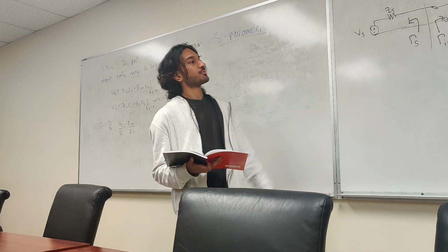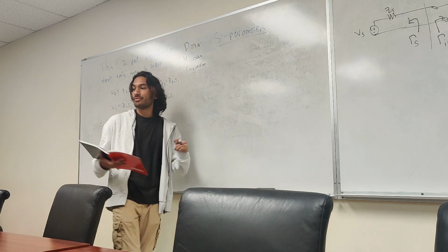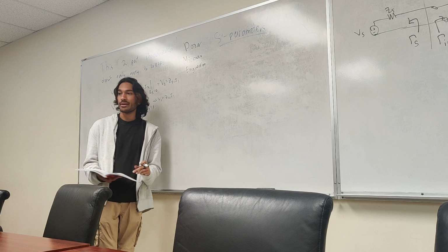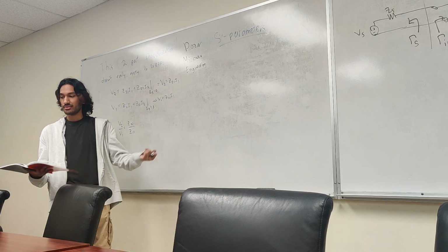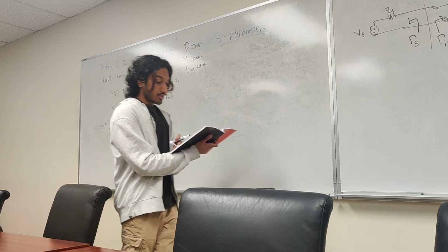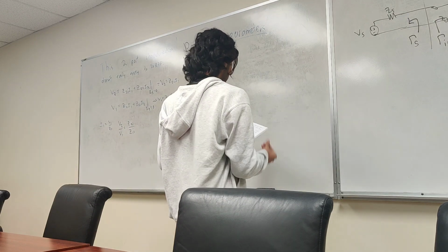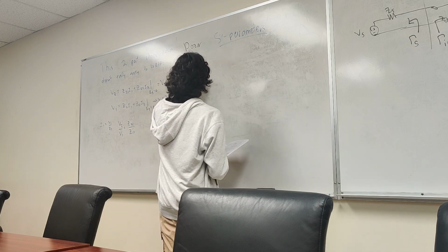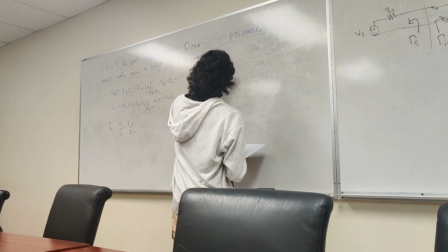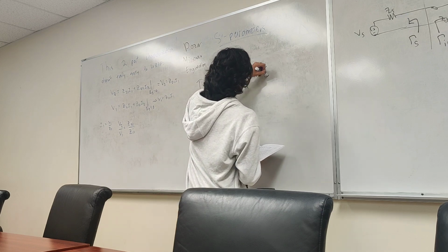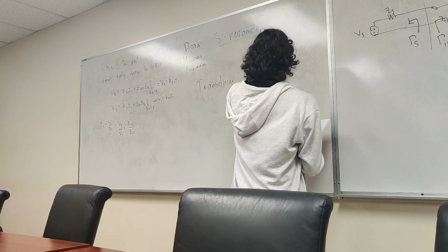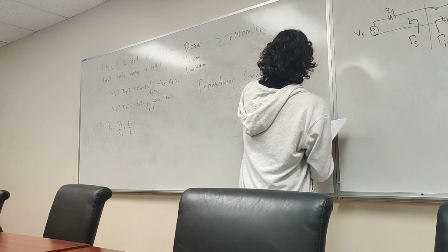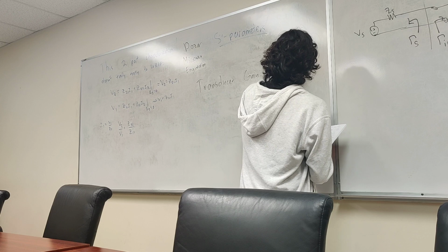So, we want to squeeze out as much gain as we can out of this transistor, so we want to define gain somehow. If we know what parameters gain consists of, then we can try to maximize it. If we have no idea what gain is related to, how can we even start to optimize? There are a few types of gain denoted in the book. I'm going to talk about one specifically, the rest aren't as important. It's called transducer gain, G_T. And I'm going to define this, by the way, in reference to this drawing here, as the power delivered to the load